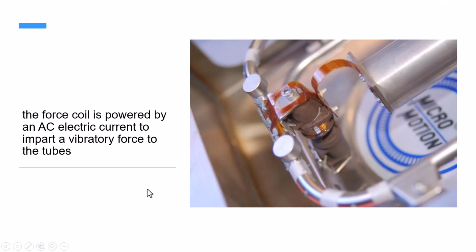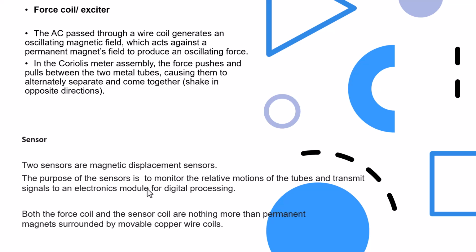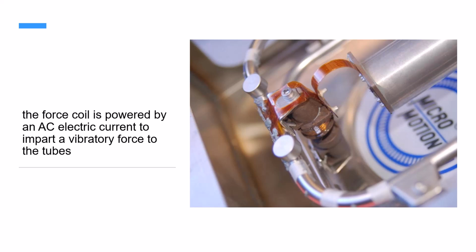The force coil and the sensor coil are all permanent magnets surrounding a copper wire coil. The force coil is powered by AC, so it imparts a vibration force to the tube, driving the tube vibration.